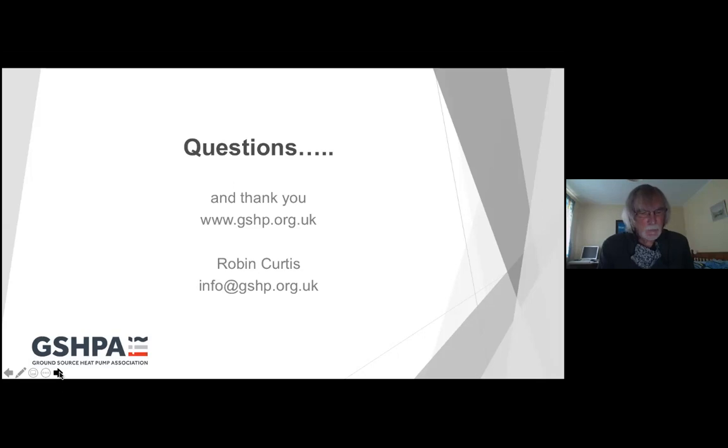Laura's asked a couple of questions, Robin. So MIS 3005 refers to MCS projects only, so sub 45 kilowatts. What about heat pump projects above that? Can the rules be applied just as well, so that it forces designers and drillers to work to similar rules? I'll answer that one first, Robin, and then come back with a second question from Laura.